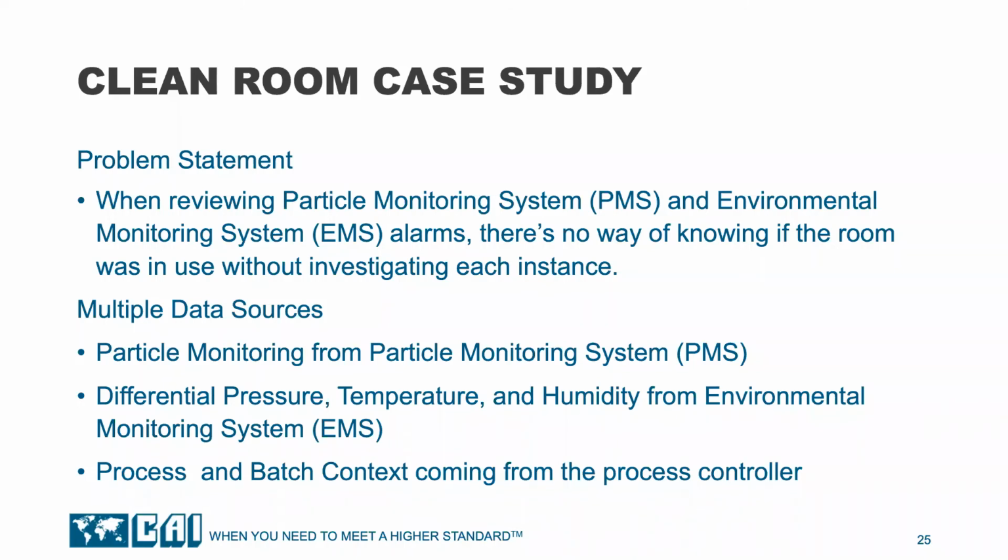Differential pressure involves measuring the pressure difference between the clean room and surrounding rooms. Our clean rooms had alarms when the DP dropped below a specified value. In our building automation system, the auditor saw a number of DP alarms and asked how we knew product had not been affected by these out-of-spec conditions. It was a good question.